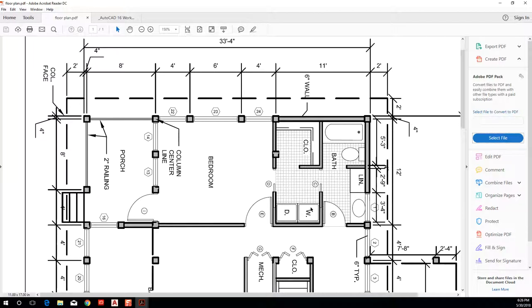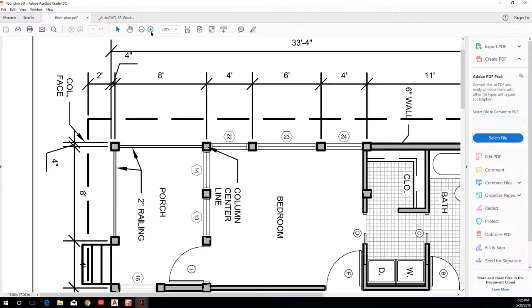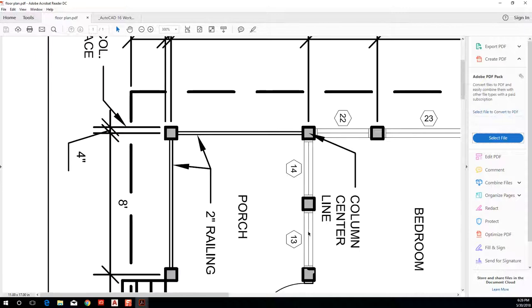And then we have tertiary architectural elements, things like furniture, appliances, countertops, millwork, right? The building could essentially exist without those elements, so they're given a light pen weight. So we have heavy, medium, and light pen weights. And then we have this fourth category of pen weights, which are going to be things like floor patterns, which are called hatches or a poche. So we have the heavy, medium, light, and then the gray tones, which are going to be the floor patterns, okay?